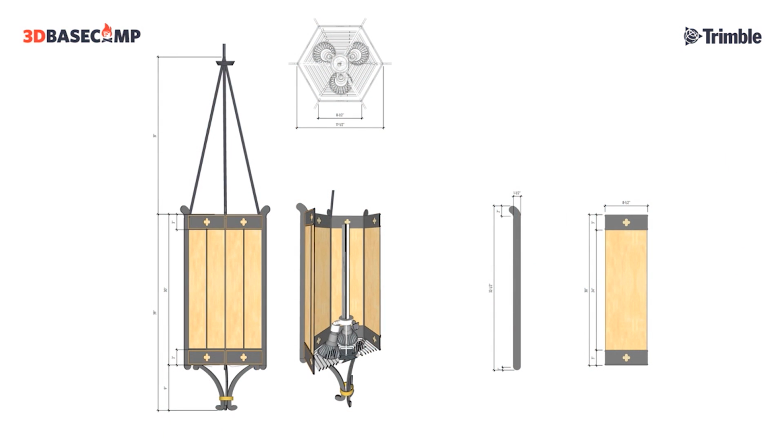Did you use the camera match for that? Oh, what did I do? The program I use for the panorama is called Pano 2VR. And in that, you can export out the exact focal length. So in SketchUp, when you go to zoom, you can set the exact focal length. I also then tried to position myself in the SketchUp model at the same position as the 360. And I knew where I put those because I did a little plan and marked all of those out.